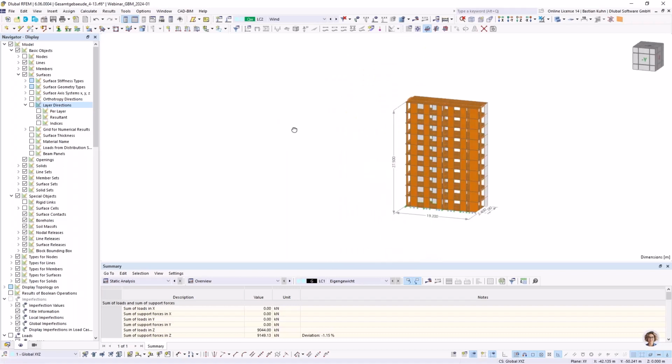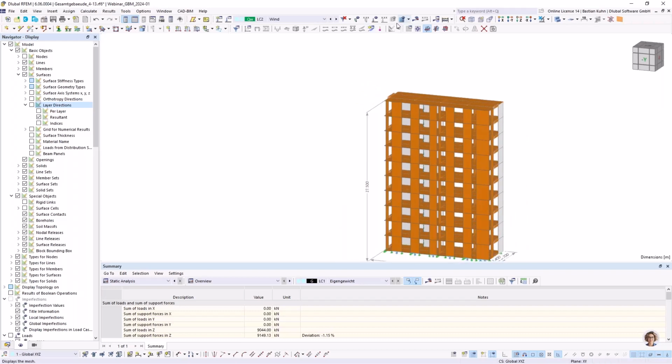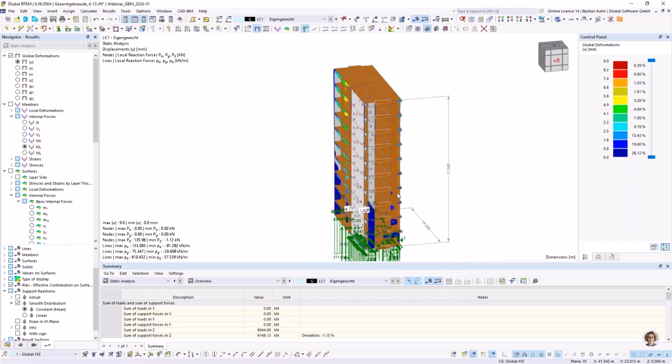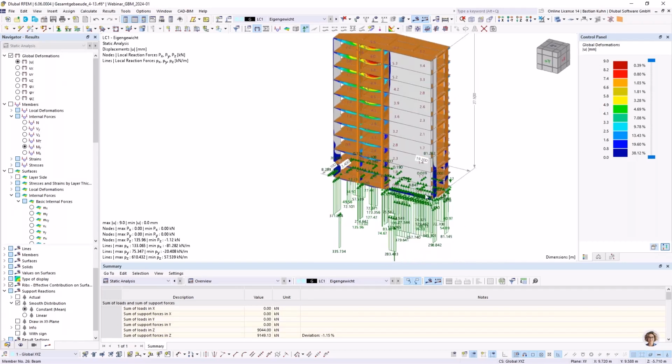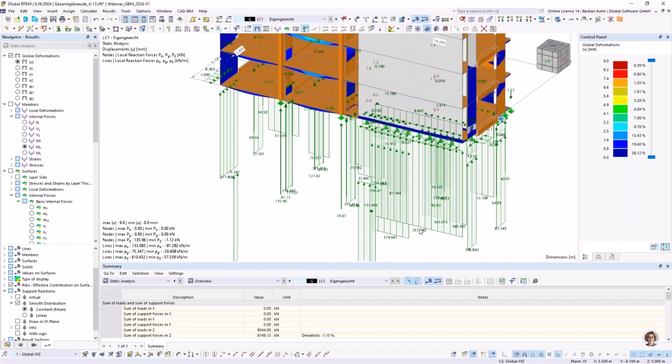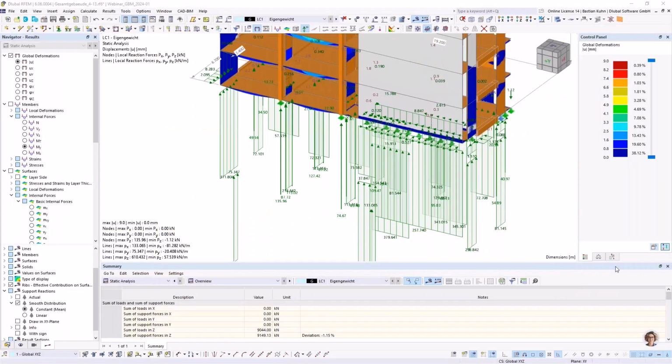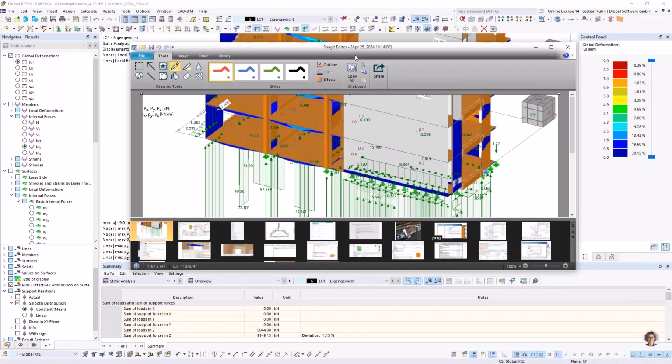Yeah, and in former times, before we had the building model add-on or this support reaction tool, customers always tried to calculate it this way. Let's say we have load case 1 with the 2 kilonewton per square meter, and we calculate it, and maybe we can remind just this little vertical force in here, 257. I can put it into my shortcuts also, so that we remember it afterwards.